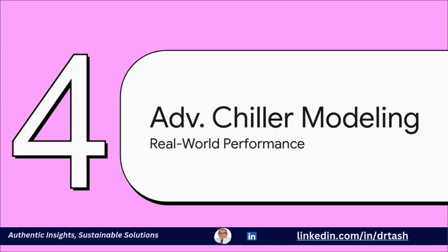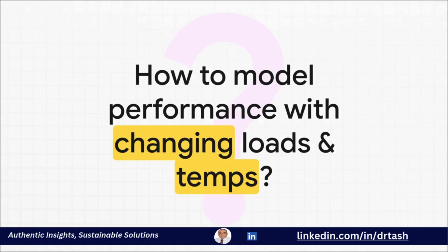Nameplate data is fine for our first pass, but if you're serious about optimizing a central plant, you have to go way beyond static ratings. We need models that can predict how these things actually behave out in the wild. This is the million-dollar question, isn't it? How do you model a machine whose efficiency is all over the map, depending on its load, the condenser water temp, on everything? A single kilowatt per ton value just doesn't cut it. It's a moving target, and we need the right math to track it.